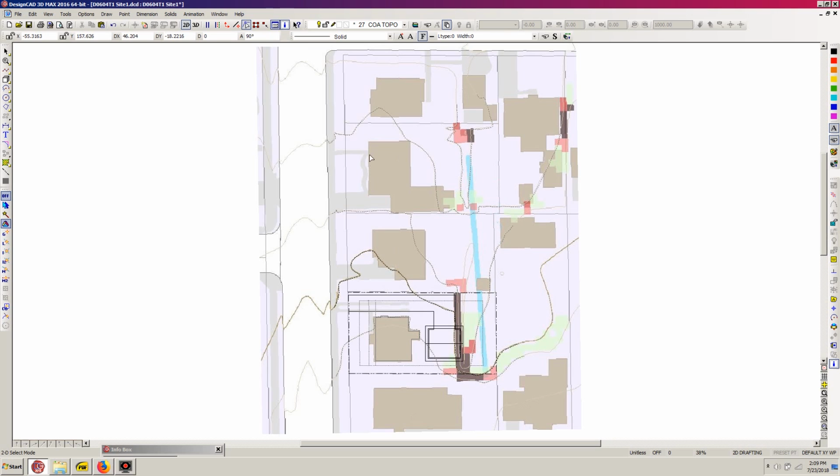Basically it's a map, and the reason I did this was because I wanted topography at least 150 feet north of the midpoint of the north-south lot dimension I'm dealing with, which is roughly in here somewhere. So I need topography at least 150 feet north of that in order to calculate what the slope is to the north for the Ashland solar setback ordinance.